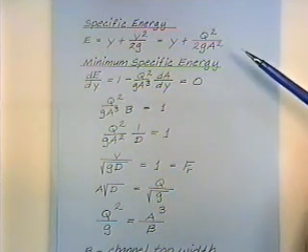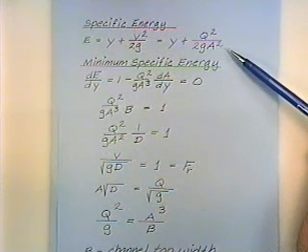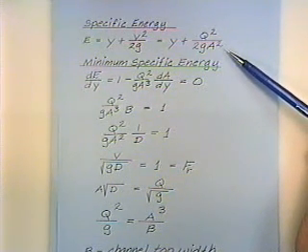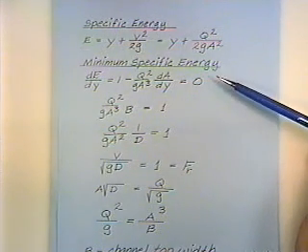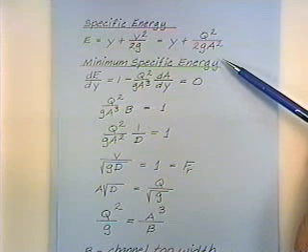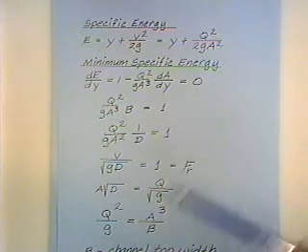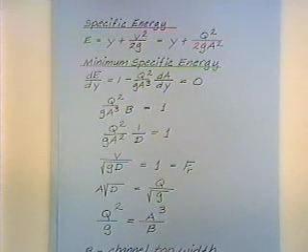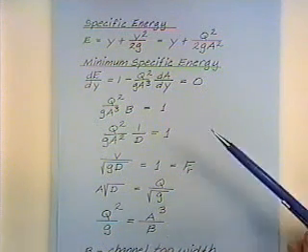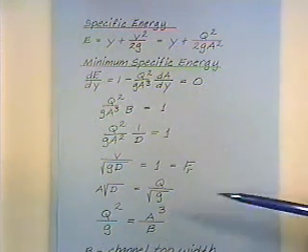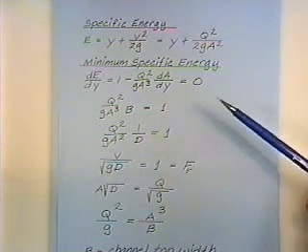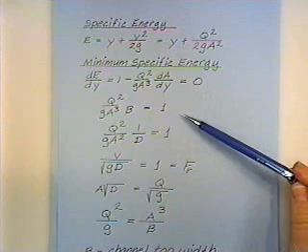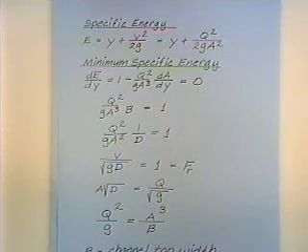If you wanted to find the depth at which this expression is a minimum and derive the equation that we'll be using, you would set the derivative of this expression equal to 0 and reduce it down. We're just going through a quick derivation here. Take the derivative with respect to y, set that equal to 0, and do some algebraic manipulations.